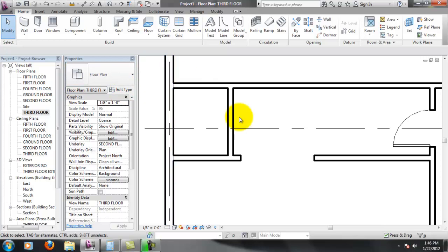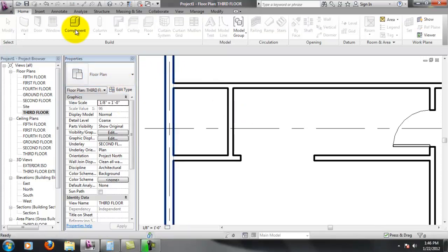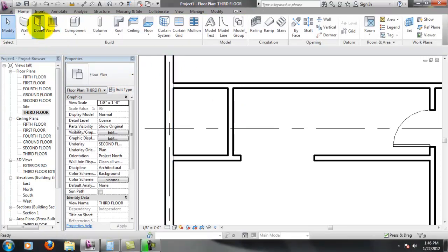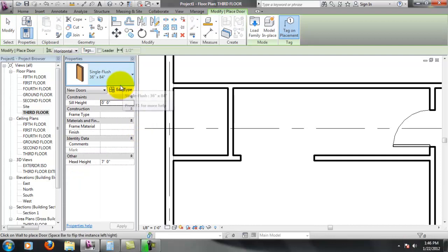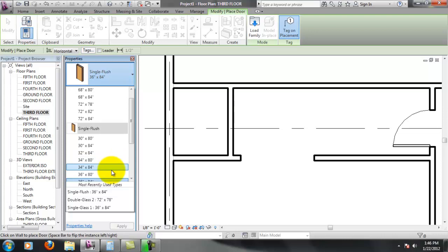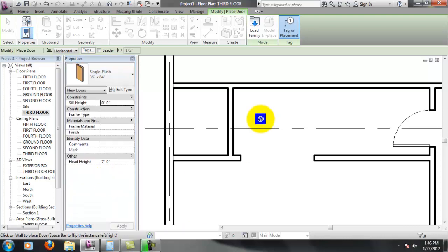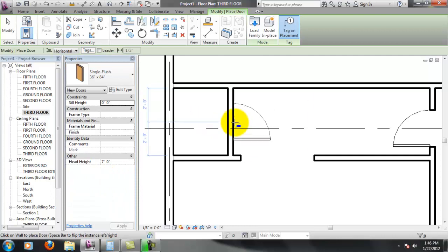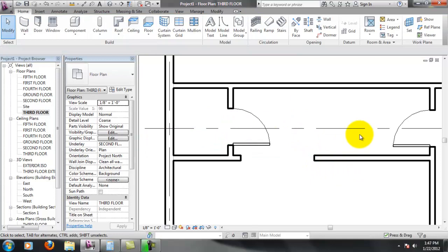Now for my janitor's closet, I don't necessarily need a 3 foot door per se. It would be nice because sometimes they're dealing with large things. Let me see if I can get away with a 36 by 84 and see what space. Yeah, that'll work. We can do that. You're going to want this door to swing to the outside though, because whatever we put inside here is not going to have room to swing. So drop that door there.